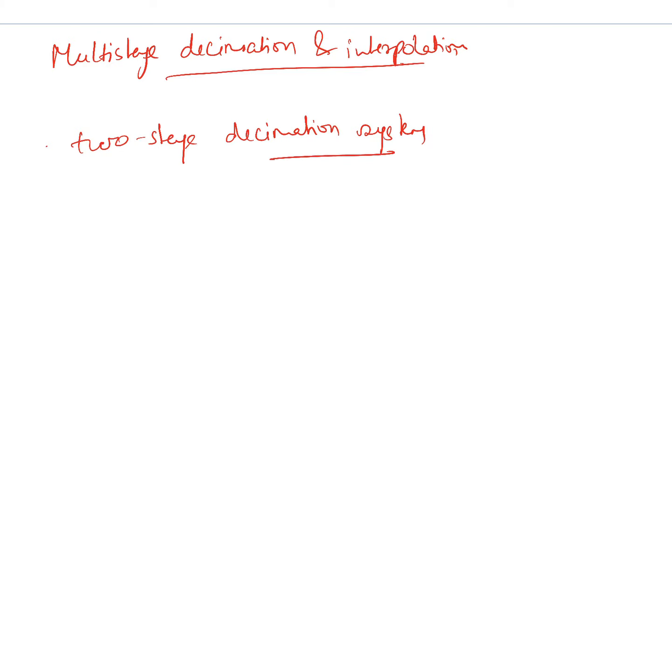Okay. So in the two-stage decimation system, let's say we want to downsample the sampling period by an integer factor M, and we can write M as a multiplication of two factors M1 and M2. Of course, they should be integers. So this is what we call the two stage. In the first stage, we shall downsample the sequence by M1.